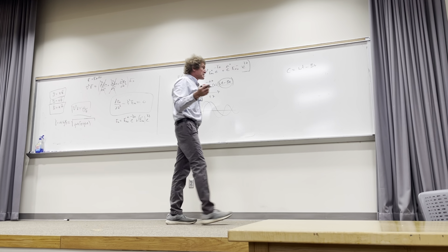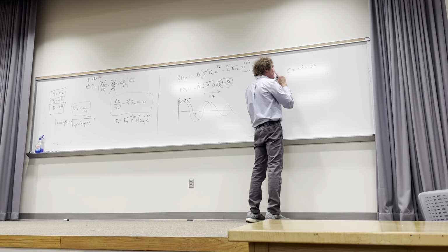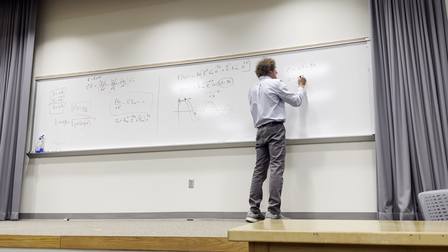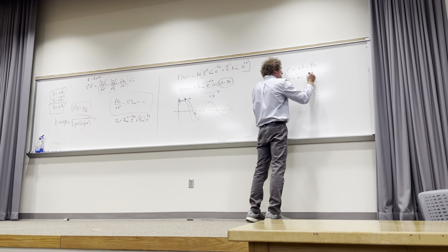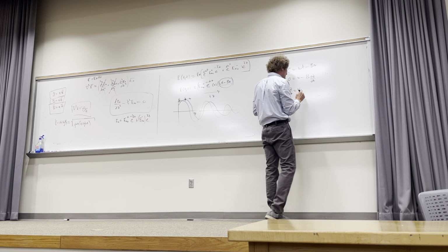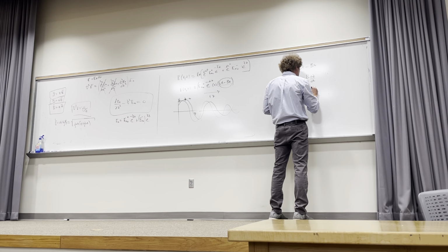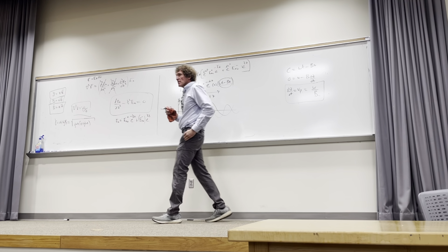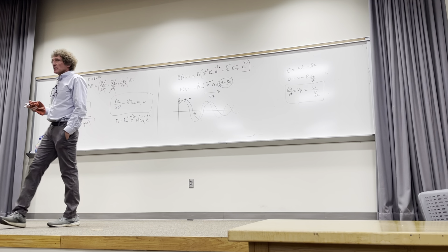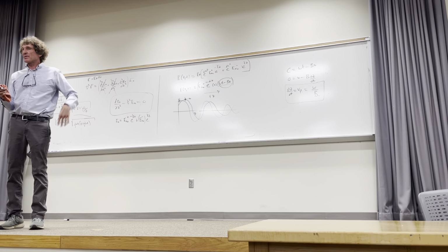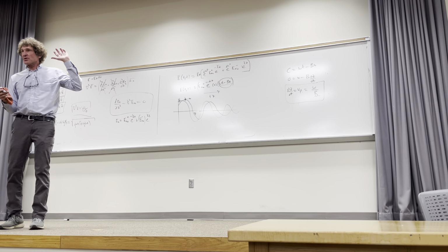The way to get phase velocity is this. Take the derivative of both sides, you get 0 with respect to t is equal to omega minus beta times dz/dt. And then dz/dt is the phase velocity of the wave, and that's equal to omega over beta. Okay? That's important. Now that's true for transmission lines as well. Do you remember that? How many remember that for transmission lines? All right, sure. That's phase velocity.